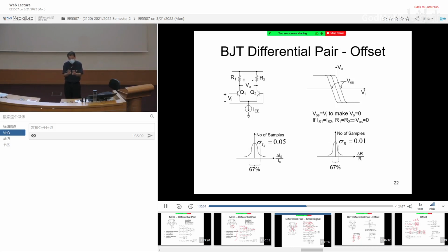So this transistor will not be matched. And then when they simulate, that's how you end up having some offset. And if you simulate more data, maybe more than 100, you will start to see the offset emerge when you cover it more than plus minus 3 sigma. So that is how in the workshop we talk about offset. But in reality, how can we understand the offset?